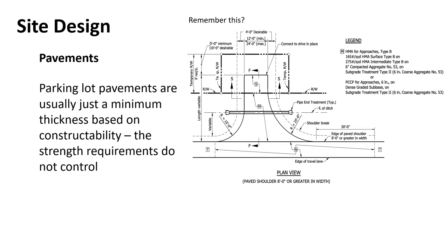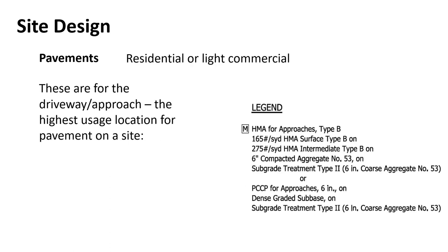And if you're going to put some wire weave in there to keep the thermal cracking down, right, you have a minimum depth of cover so that it doesn't corrode from the salt from the road and so forth. All these things set up that minimum depth, and so that's what controls. In this case, it's not the strength of the pavements. So remember that next year when you're taking senior design.